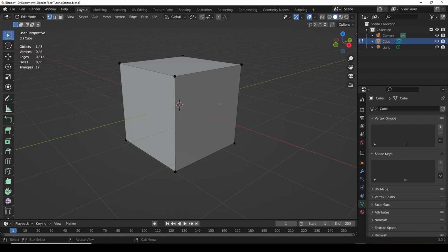When we are modifying our geometry, we're going to want to be able to access separately either the vertices, like you have here, or the edges, or the faces. And to do that, you can select up here, right next to this drop-down, these 3 modes are the selection modes. The far left, you got this little dot. This is vertex selection mode, which we're in now. So I can click on a vertex and I can select it. I can click on this and select that. Or I can drag select and select those 3.